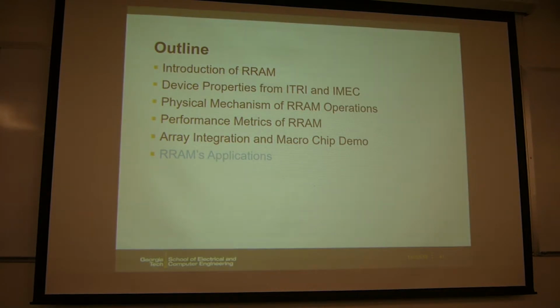Okay, so those are the demonstrations from the industry in the past 10 years. And the recent chips achieve like gigabit density, like 16 gigabit or 32 gigabit. So this is similar to, let's say, the 3D XPoint kind of density. And if you look at the initial design of SanDisk and Toshiba, it is very much like the 3D XPoint design. But they didn't make it eventually, because I think the yield and the reliability are still concerns for those prototypes.